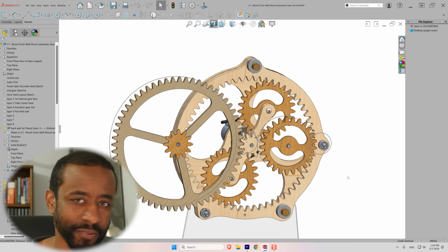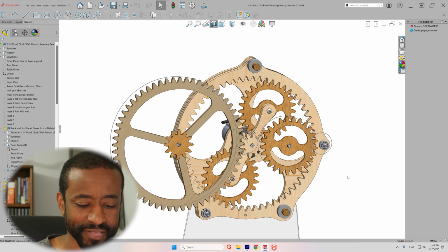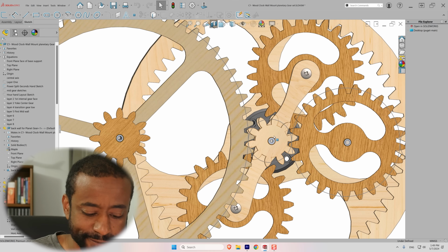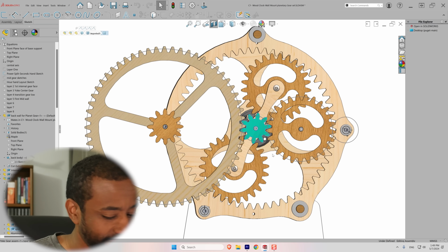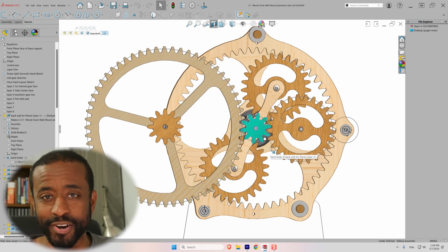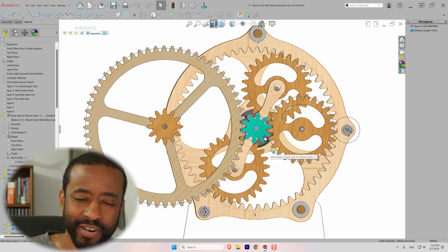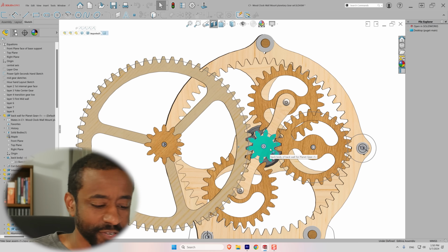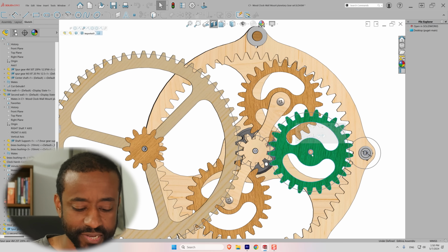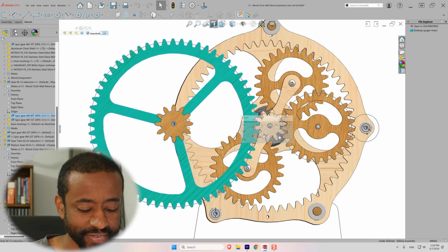I had this one problem that I struggled with for a while in the back of the clock, and that was at layer 2. If you look here, you can see there's a little gear, and I needed a 6-to-1 gear. I mean, that one's got 10 teeth, and like I told you earlier, I normally don't go below 12, but I really needed to get 6-to-1, which means this one should be 60. And it is. And so I needed to position this gear, and this gear.